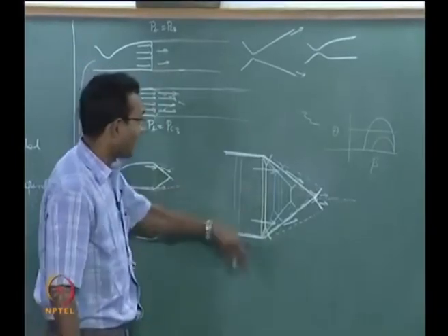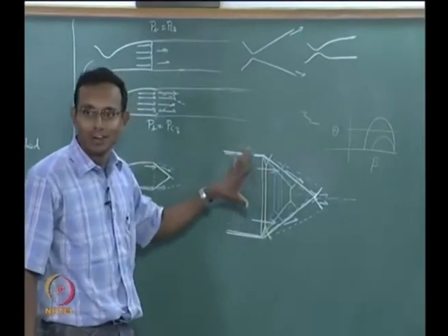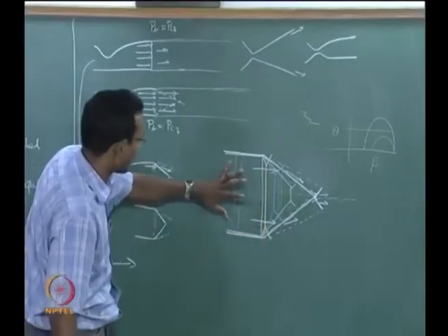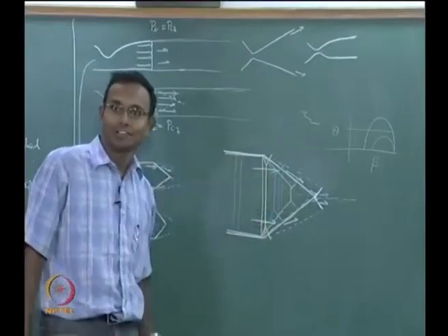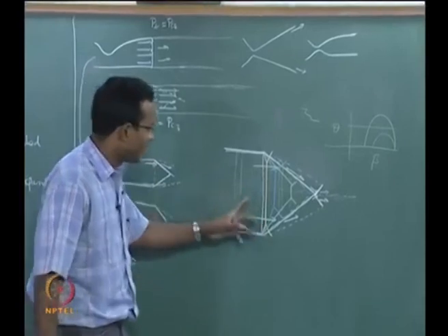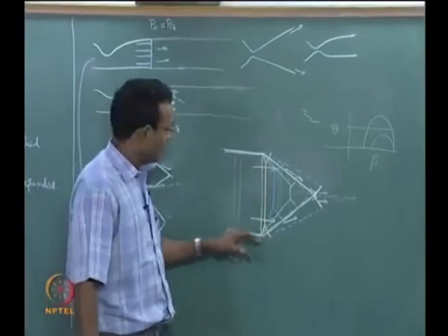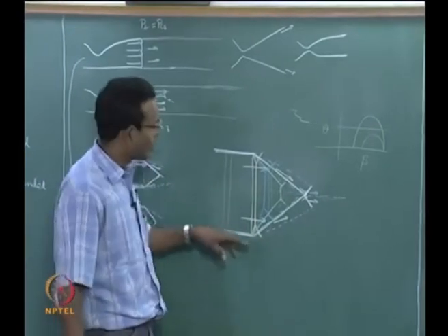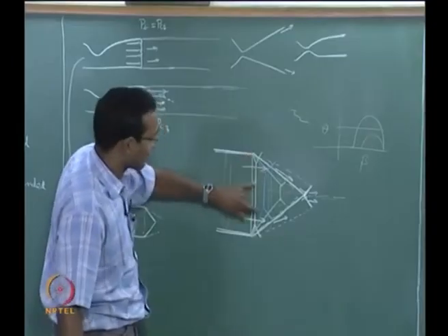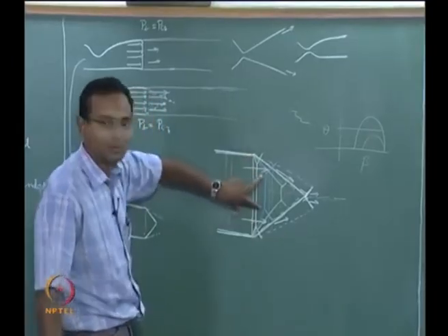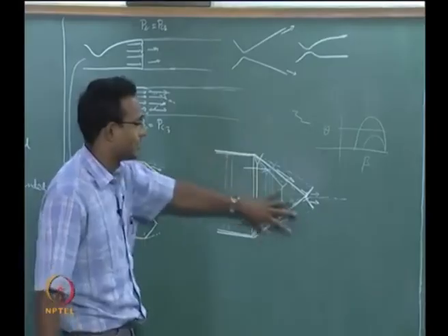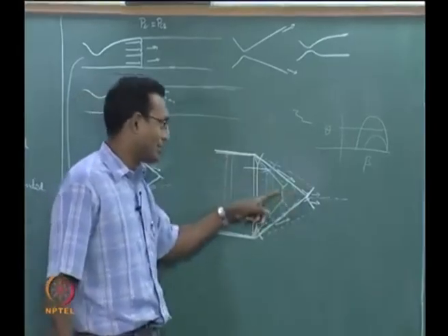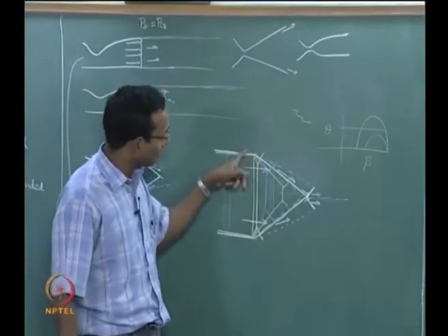So on an average this slab of fluid has shrunk. When I decrease pressure more, it needs a lot more change, so it goes to a point where more of oblique shock is happening, less of normal shock is happening, and it just continues like this. Eventually there will be a point where there is no more normal shock, the whole thing is oblique shock.